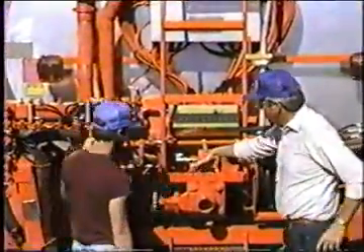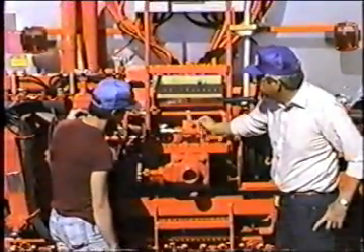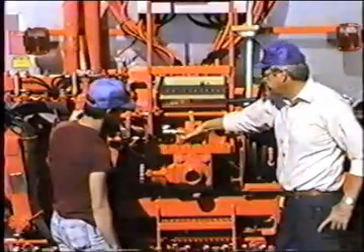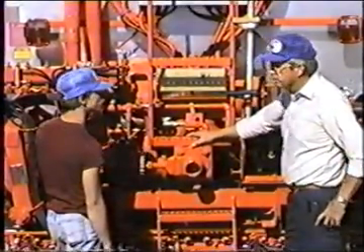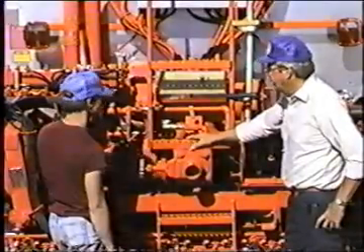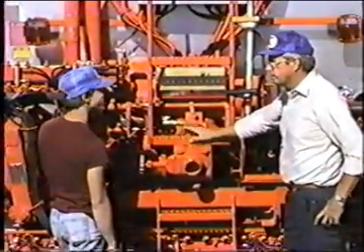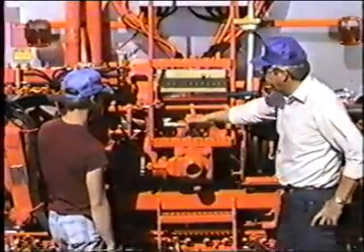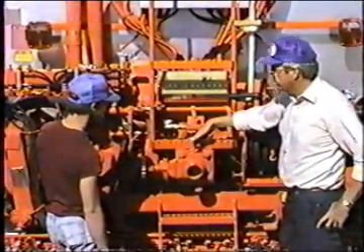This box is the intake strainer, and that 4-inch line from the tank valve comes into this strainer. This has a screen inside it. It has a cylindrical screen with 1/4-inch holes in it, and those are to catch the nuts and the bolts and the eyeglass cases, cigarette packs and hats. Everything that ends up in an asphalt tank gets caught right here at this screen.